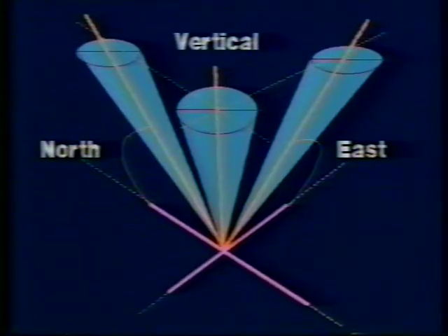How does a non-moving antenna work? Well, we have to steer the beam to at least three beam pointing positions to measure the vector wind. We have to look vertically to measure the vertical wind, and we have to look off axis to the north and the east to measure the east and north components of the wind. And we do this with what's called a phased array antenna. That is, different parts of the antenna are excited with different phases. And the resultant combination of the summation of all the infinitesimal elements on the antenna radiating points the beam. And this is what we call a phased array antenna. So it's basically steered by phasing different parts of the excitation on the antenna.